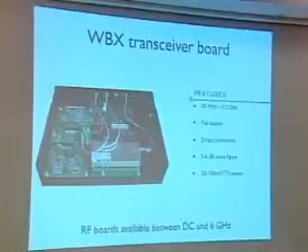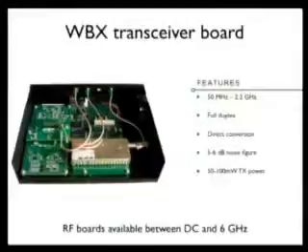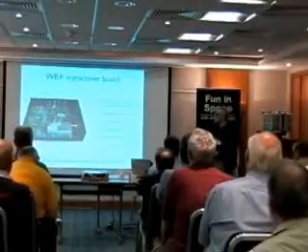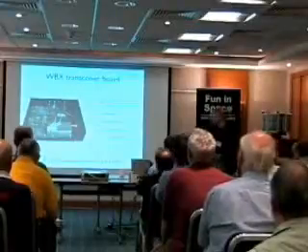It's a full duplex transceiver. It has a quite good direct conversion receiver. You can see the noise figure is around 5 to 6 dB, depending on which end of the band you are. And it can even give up to 100 milliwatts of transmitter power. So it's very good. It costs around $450, I think, but I think it's good value for money.